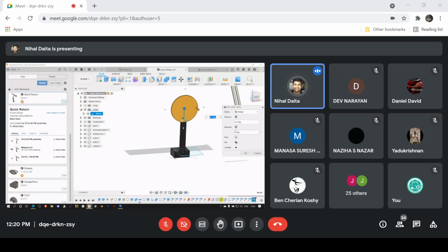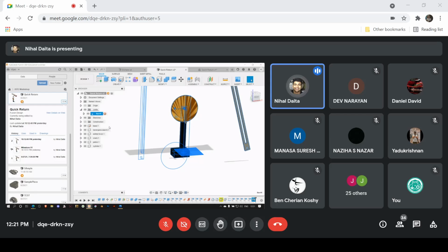Edit joint limit, yeah. The maximum should be 90. Yeah. So if I did this right, it cannot go any further than that. It just gets locked there. So for Revolute or sliders, all of these options apply. So let me just remove those joint limits. Edit joint limits, minimum is 90. And I just remove the limits altogether. It's fine. It just needs to stay there.